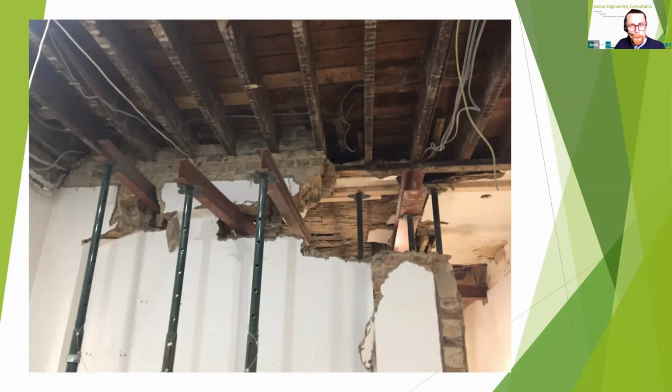So this is a project we had no involvement in until we got called out, once it was identified that things weren't going too well. This was a domestic builder who was way out of their depth. The wall is basically falling down here, and the floor above is unsupported in places. There's no bracing to the props, and there's no positive connection between the prop heads and the lintel.